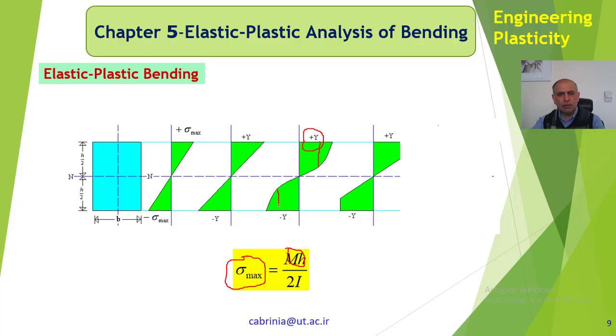For this curve, y is here, minus y is here, from there to there, and minus plus y also from there to there, not to here. Okay, but here, because we have this rigid plastic, once we reach this value, it remains the same. So stresses here are all the same, equal to y, because it's elastic, rigid plastic.